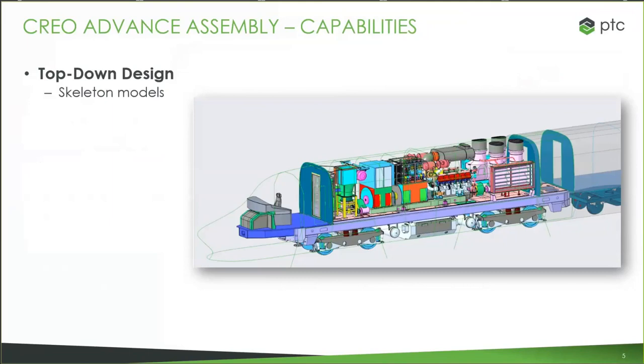And it can also define motion skeletons to support mechanism design and evaluation. And then at that point, you can distribute this data to establish design criteria and support concurrent development. So you're going to share these lines and curves and surfaces with whatever group might need them to start building their parts, to start building their geometry. That way you can control the references and control the shape.